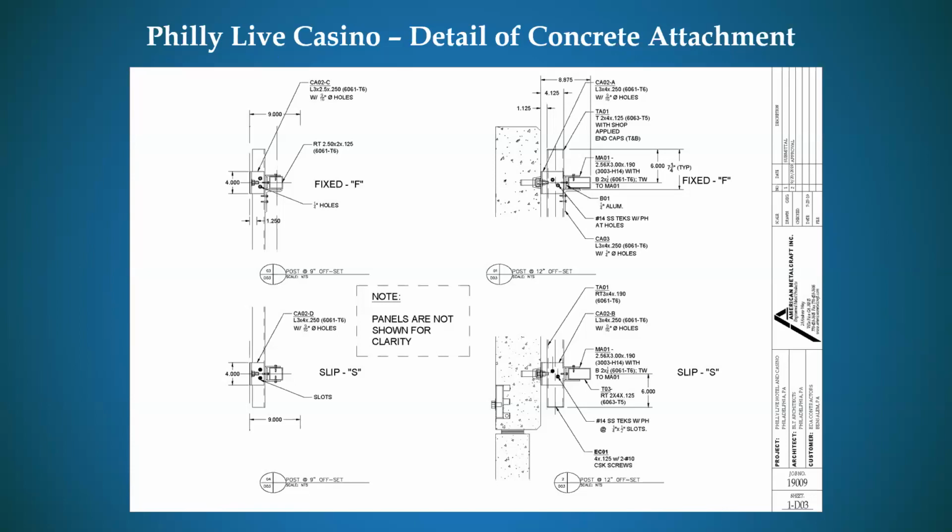This particular project was for a parking garage, and you'll see through the details the anchor bolts going to the concrete. We got together with the concrete folks and figured out the strength of their concrete, where their embeds are, and did various calculations to determine how often we need to fasten into that concrete.